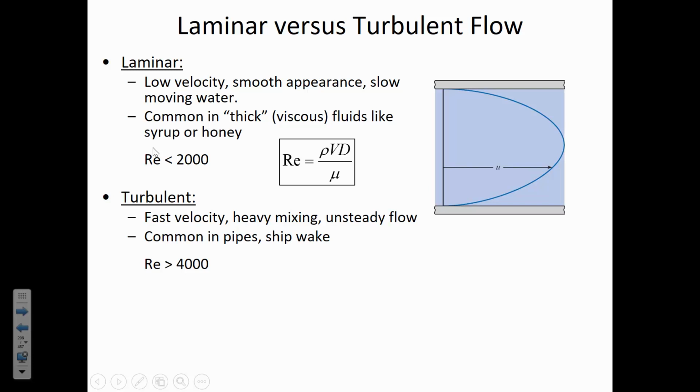Flow conditions will stay laminar if you have been previously laminar. If you're coming from the turbulent side, like if you had a really fast-moving water velocity and it was already turbulent, but you're closing the valve now, so you're decreasing the velocity, it would stay turbulent until you got to the 2,000 threshold, approximately.